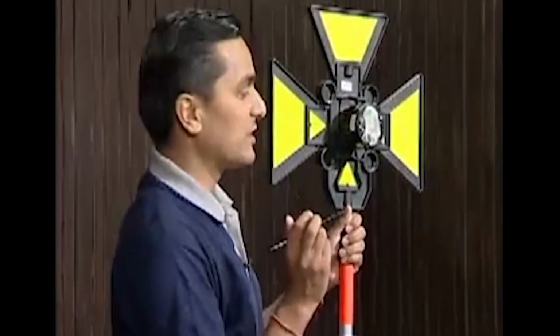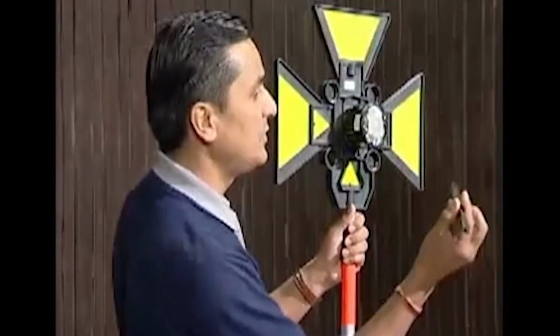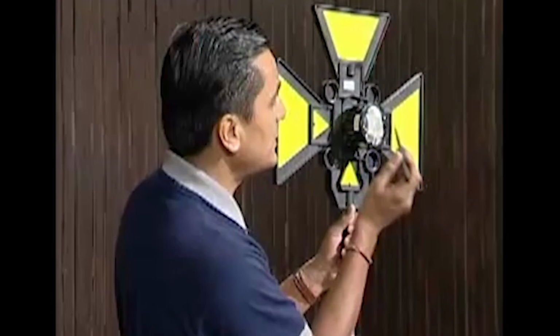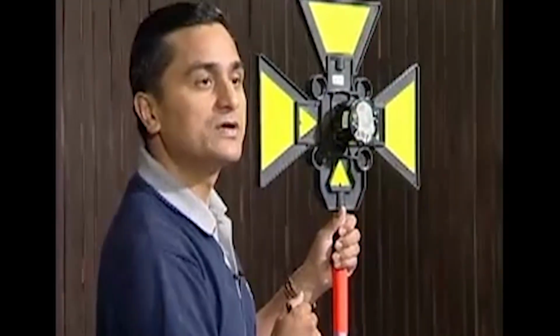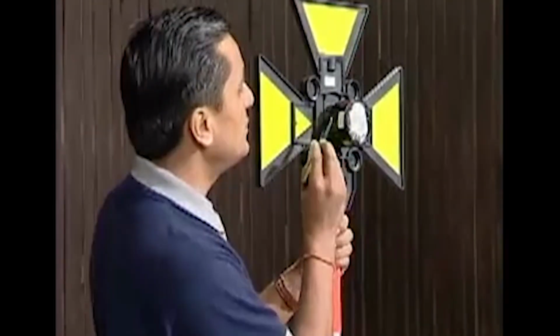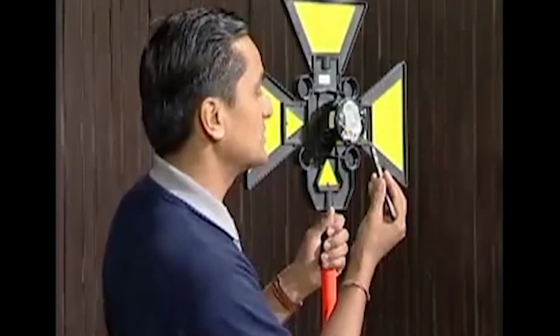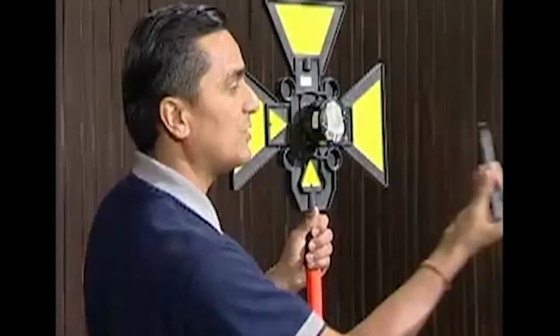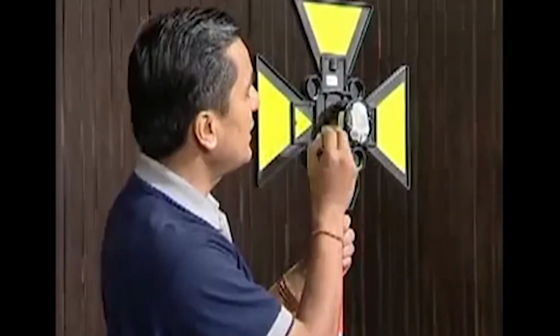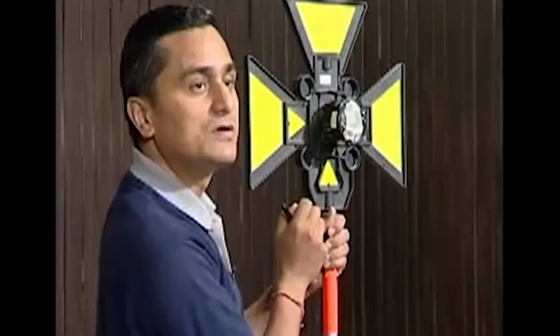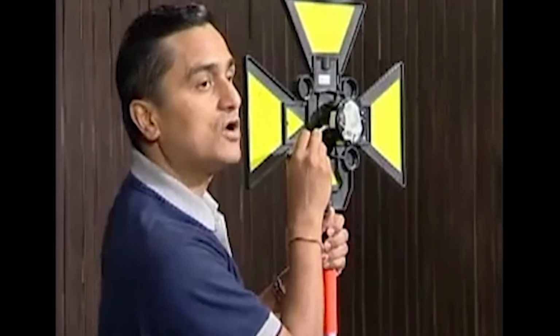Then if you look into the target, we'll talk about the target correction. Here in the case of the target, as we are seeing, the laser pulse or the electromagnetic radiation will come over here, will get into the prism and will get reflected. Now the refractive index of the medium here and the medium there inside is different. What we are measuring, we are assuming that it is reflecting back, and all through in our computations we are using the refractive index of this medium.